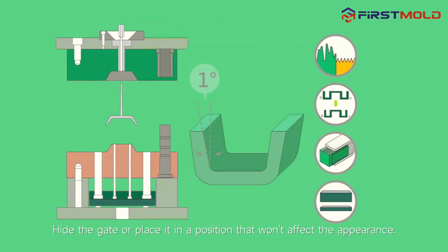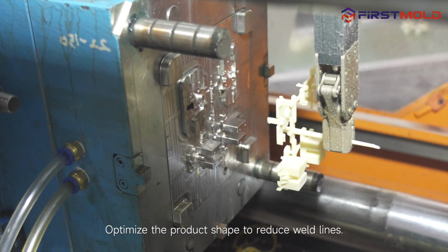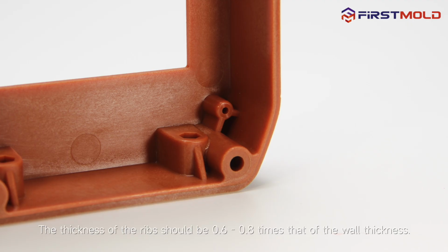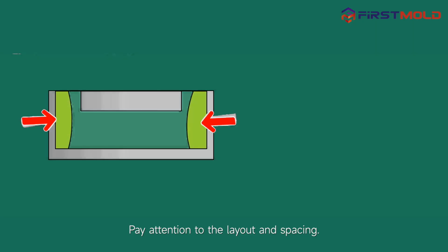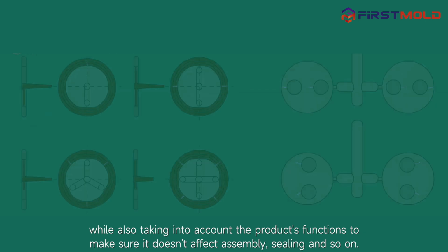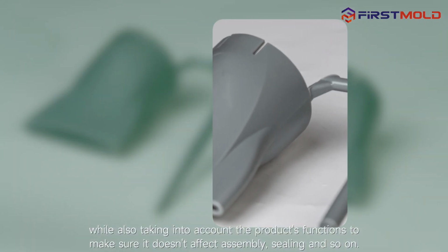Hide the gate or place it in a position that won't affect the appearance. Optimize the product shape to reduce weld lines. Reasonably set ribs inside to enhance stability. The thickness of the ribs should be 0.8 times that of the wall thickness. Pay attention to the layout and spacing. Place them in a position where they have little impact on the appearance while also taking into account the product's functions, to make sure they don't affect assembly, sealing, and so on.